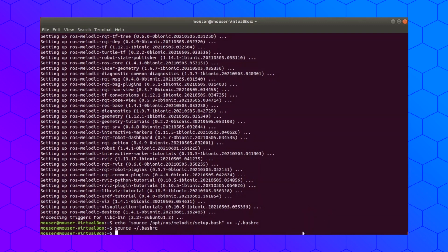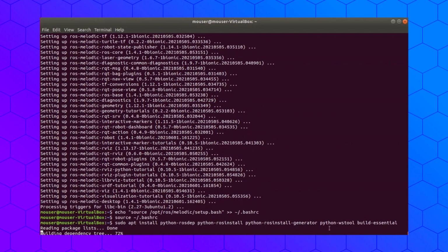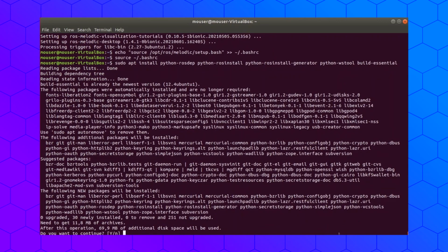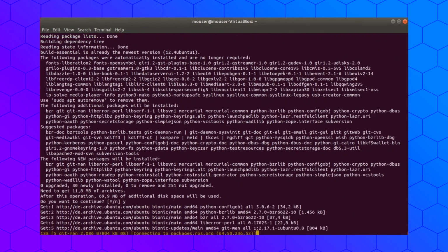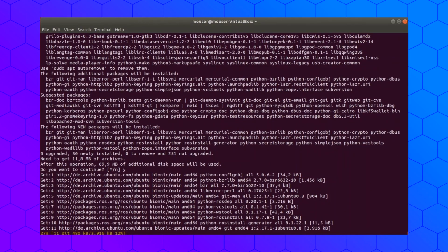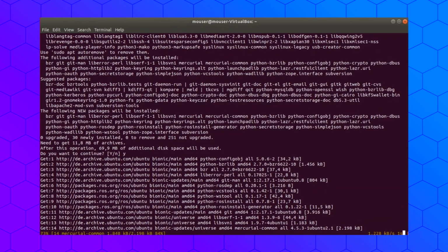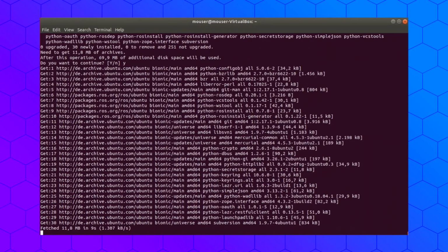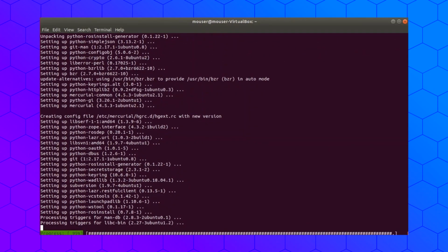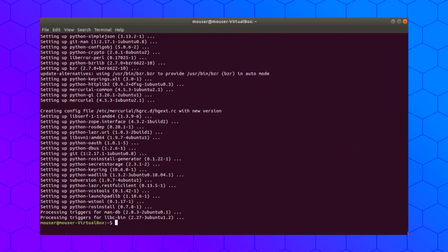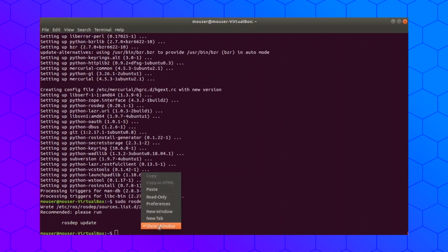Now that ROS Melodic is installed, we will proceed with installing the Intel RealSense SDK 2.0. The SDK is a cross-platform library for the RealSense depth cameras. It provides intrinsic and extrinsic calibration information, depth and color streaming, as well as synthetic streams, such as point cloud, depth aligned to color, and vice versa. To install the SDK, unplug any connected Intel RealSense cameras and follow these steps.